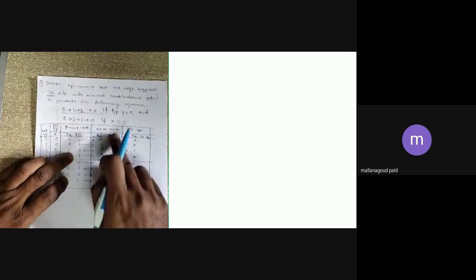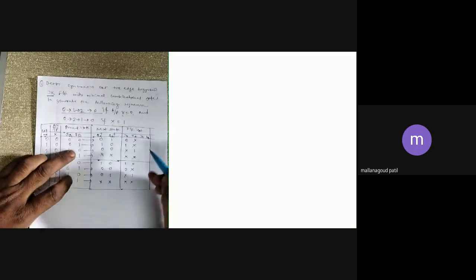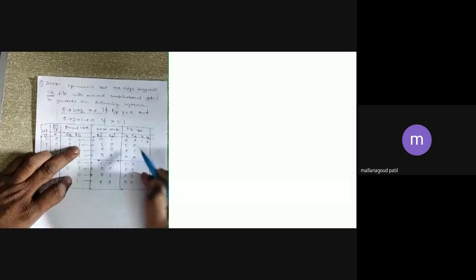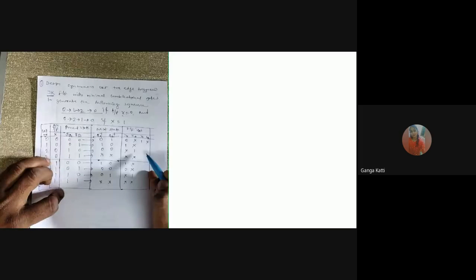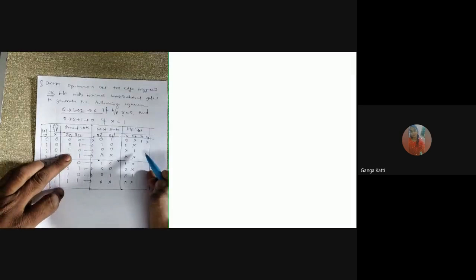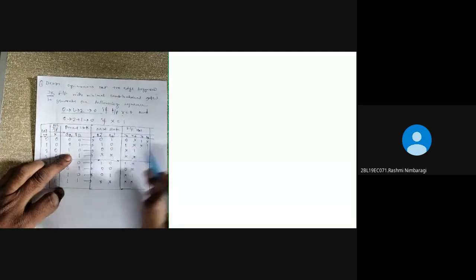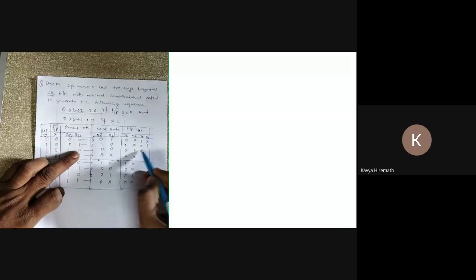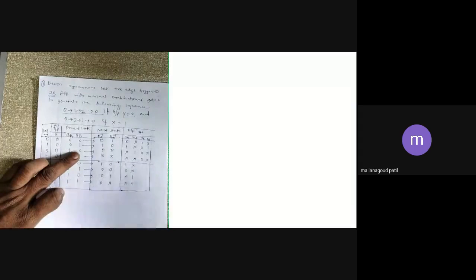Similarly, you write QB. QB to QB plus, you have to write 0 to 1, 1 and don't care, 1 to 0, don't care and 1, don't care 1, 0 to 0, 0 don't care. Then this combination is don't care.